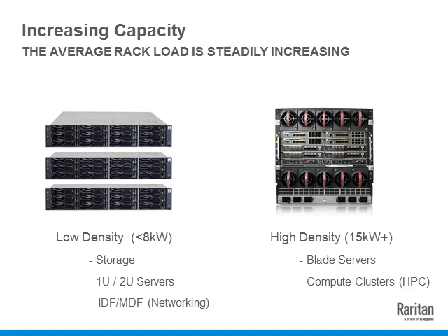On an average, if you looked at 5 years back, if you asked a data center operator or a designer, what is your average rack density? The answer could have been somewhere in the range of 5 kilowatts. And that used to be considered the average, which you could say like medium density. And there would be leading edge players running at 12 kilowatts. That will be considered high density.